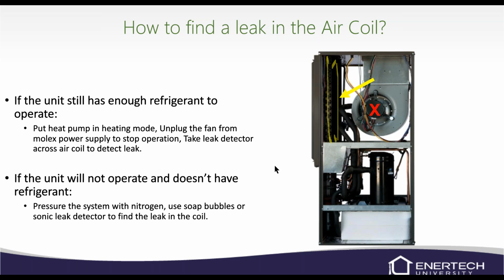But the easiest way is to use a leak detector and then look at the coil real closely and look for oil. We've got an old Johnson Controls plug-in electronic leak detector that we use that works real well. I think I had a TechMate that I used quite a bit that I trusted. So it's usually just finding one that you trust and know how to use. Sometimes those electronic leak detectors can be a little touchy. So again, soap bubbles just don't work the best.